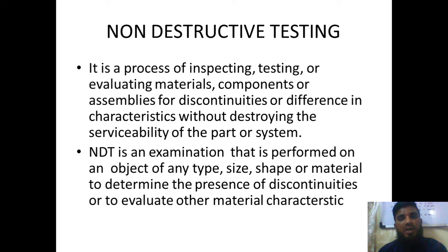That is the most advantage of non-destructive testing. If you want to test that without non-destructive testing, then you have to take out the connecting rod from your automobile, and you have to go for different kinds of tests, like a hardness test, then an impact test. Different types of tests need to be carried out only when it is taken out. So once destructive testing is carried out, the material will be wasted. Again you have to make a new material.